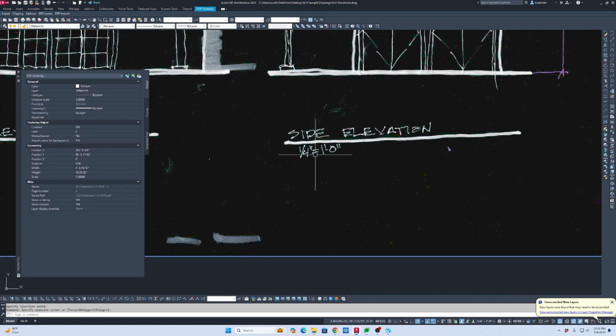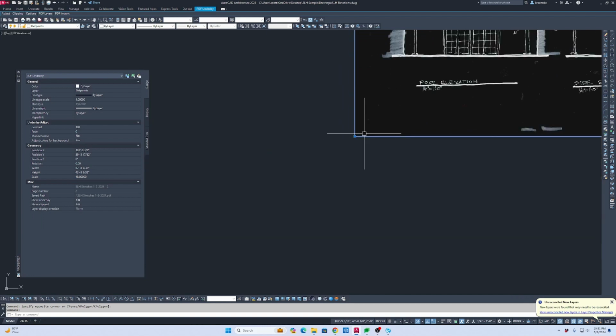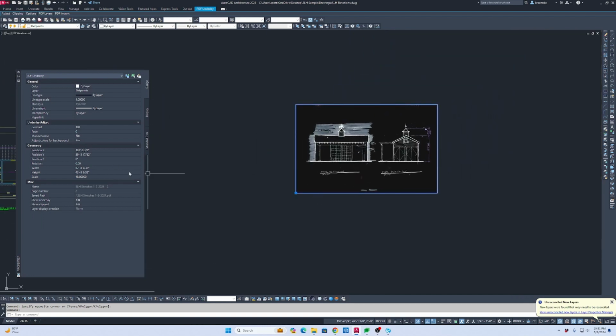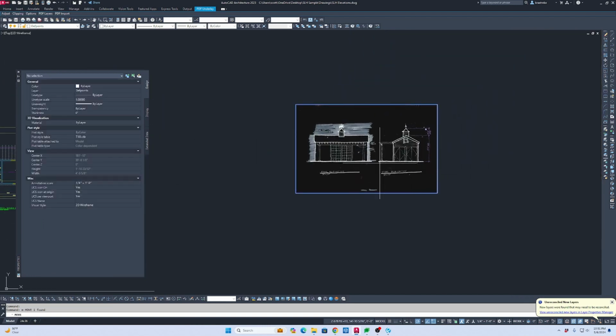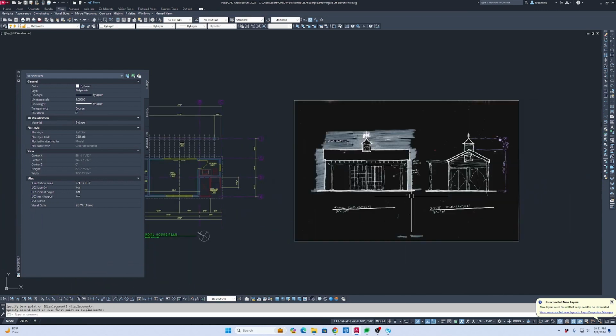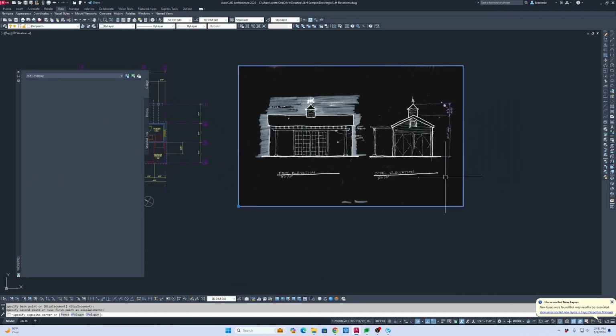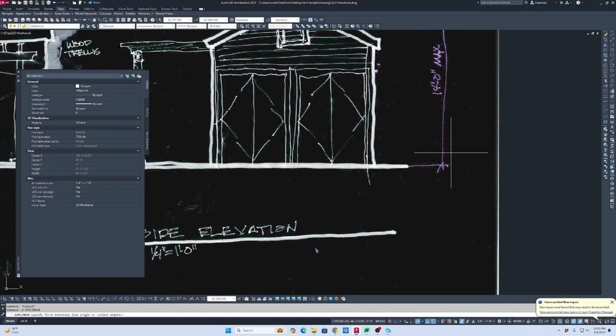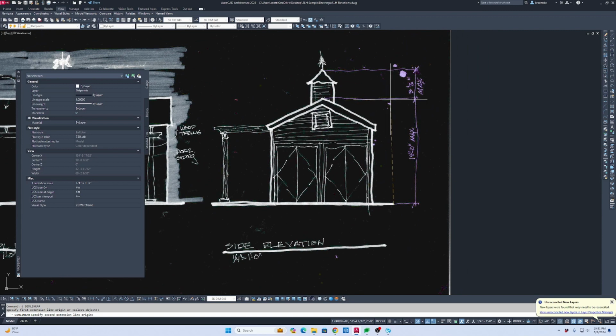They say quarter, so if I make that scale of 48, that will equal quarter scale. The reason 48 works, if you're unfamiliar with that in CAD, is because there are 48 quarter inches in a foot. And so we're trying to bring that to real world scale, so that's why that equals 48. So let's see if this is pretty close. 14 feet. Yeah, okay, so that's 13 right now. Okay, so it's drawn a little bit smaller.